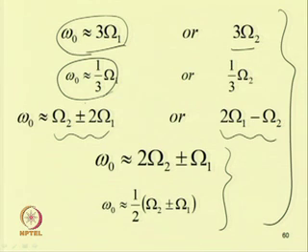By taking different resonance conditions, first we have to write the reduced equation, then in this reduced equation we have to substitute the time varying term equal to 0 to get the steady state solution. From the steady state solution we have to find the frequency amplitude relation equation, and from that we can obtain either a closed form solution, or in case of a multi degree of freedom system we can get a set of equations.